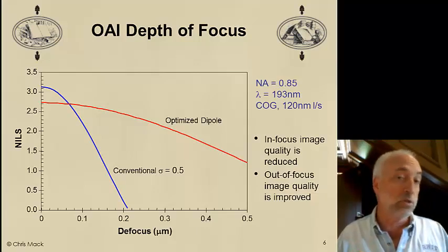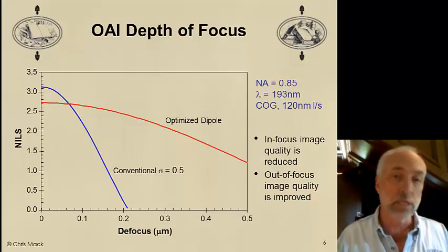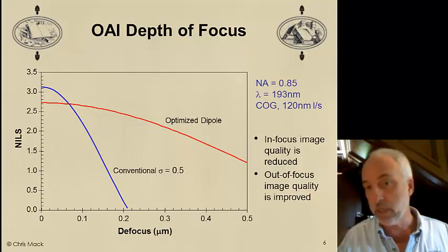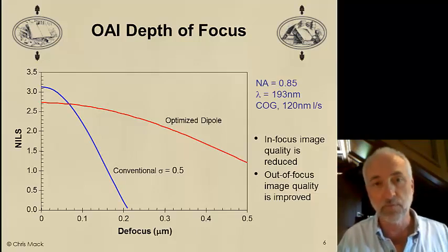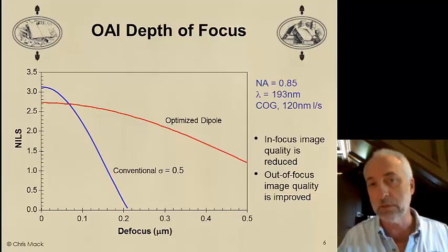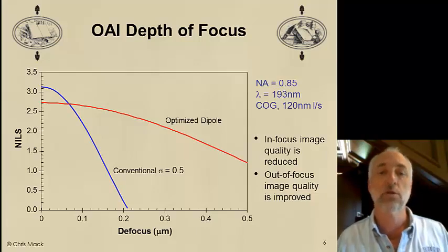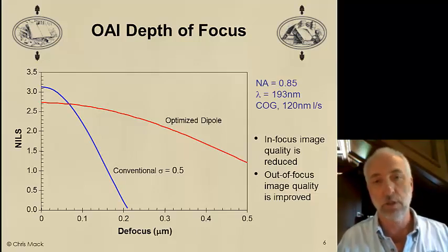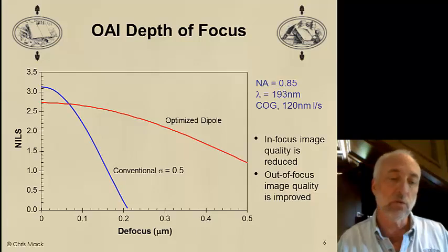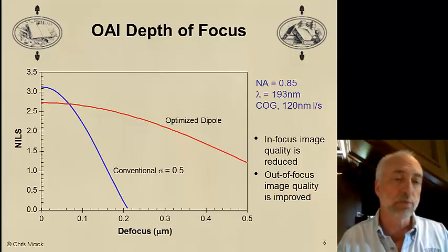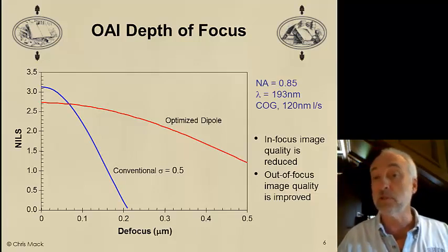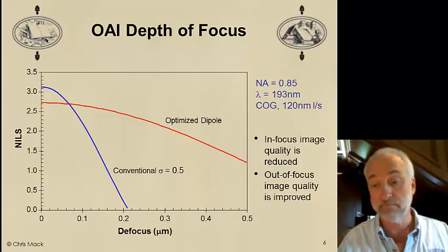Why off-axis illumination is almost universally used today when printing high-resolution features. It's extremely important in the industry. An important caveat, though, we can only optimize our illumination for a particular pitch. And that means we have trouble printing high-resolution features at multiple pitches at the same time.